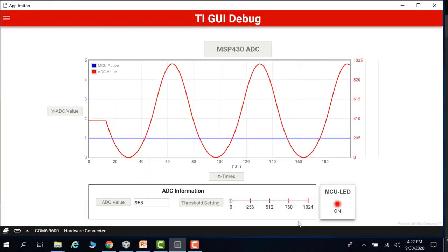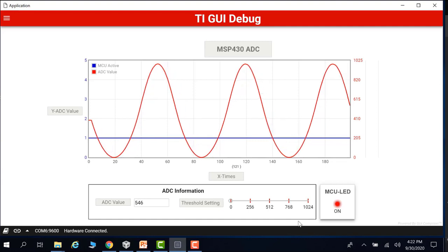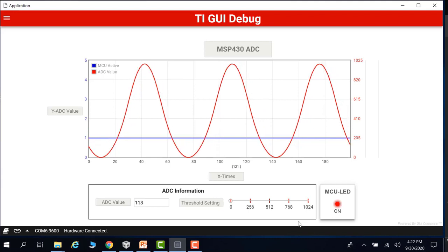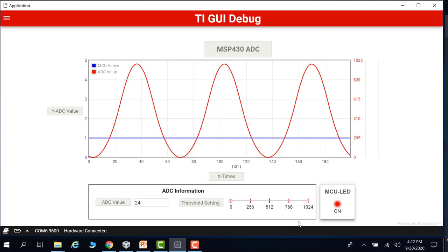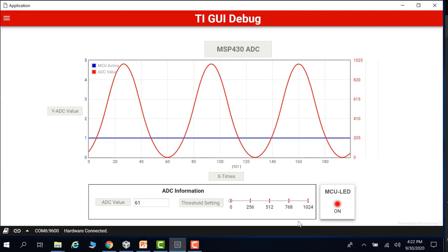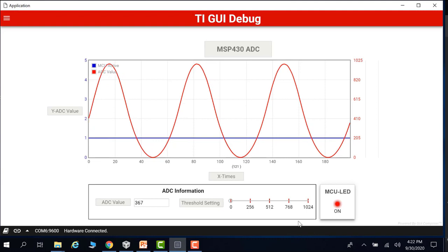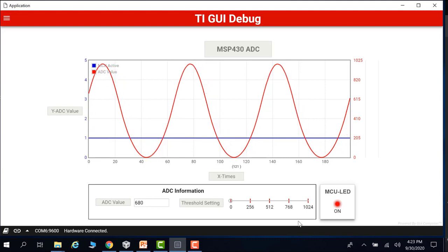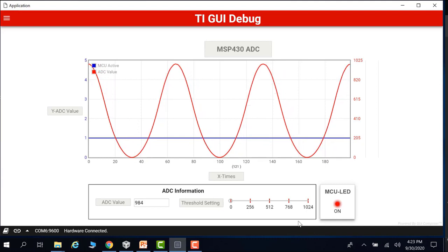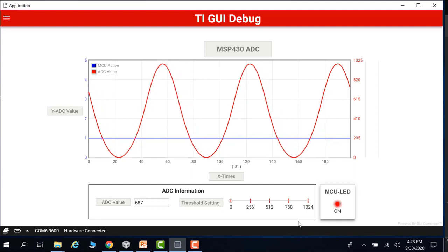Hi, are you looking for a super easy way to monitor variable analog signals with extremely low power consumption? Well, then you've come to the right place. This video is part of our Housekeeping MCU training series, and here we demonstrate how to use the Integrated Analog to Digital Converter, or ADC, to interface with other devices on a board for applications such as battery monitors or temperature sensors. In this specific example, we will show you how to use the integrated ADC to periodically sample incoming analog devices to wake up the MCU when a threshold is being crossed.